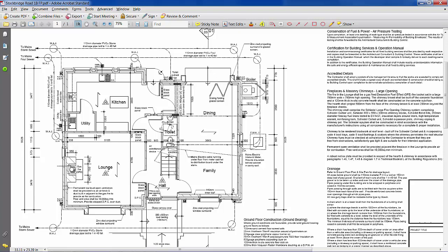There is a smoke detector in the lounge, and then there's a heat detector in the kitchen. No smoke detector there because it's more likely to go off in the kitchen if somebody just simply burns the toast or something like that. And then some of the walls in this dwelling are glass block panels. This wall here I think is a stud wall,